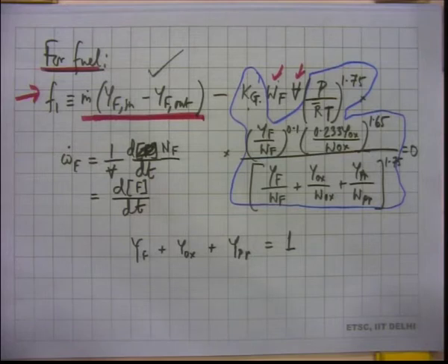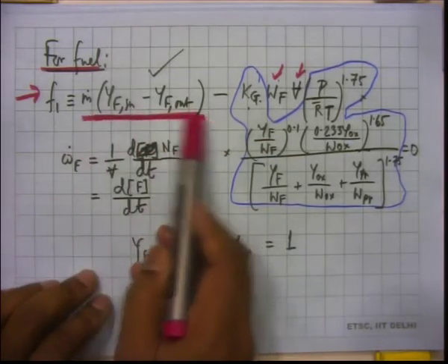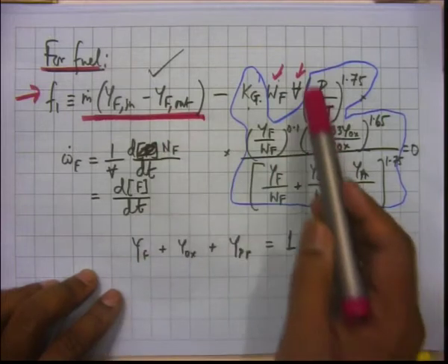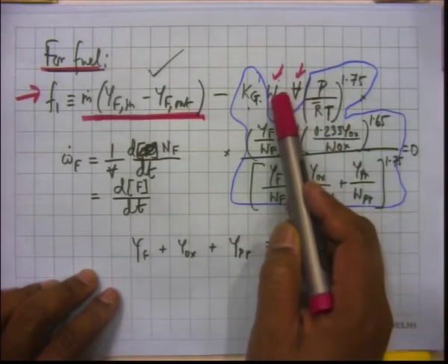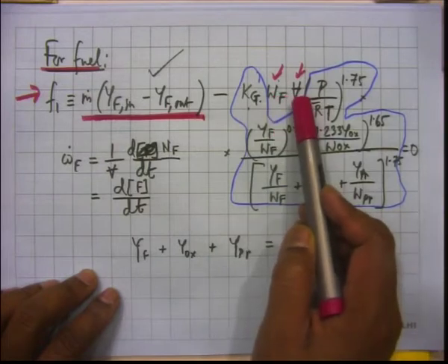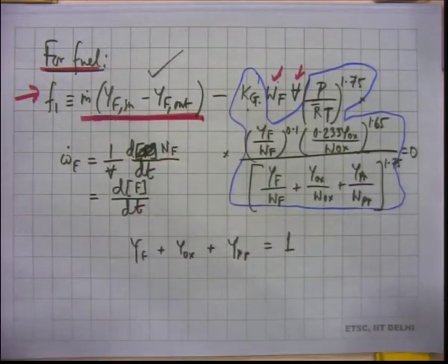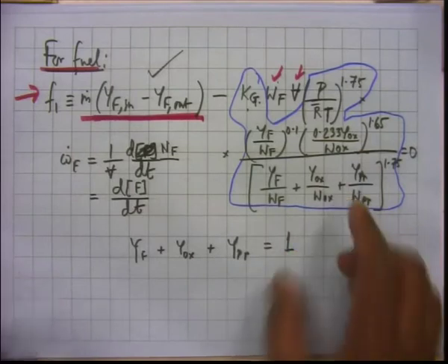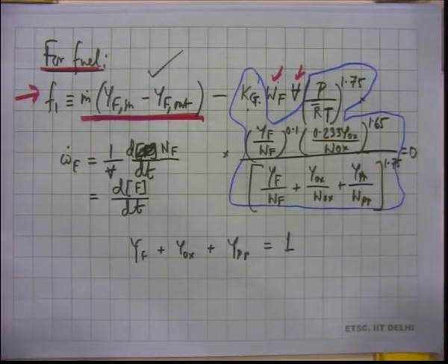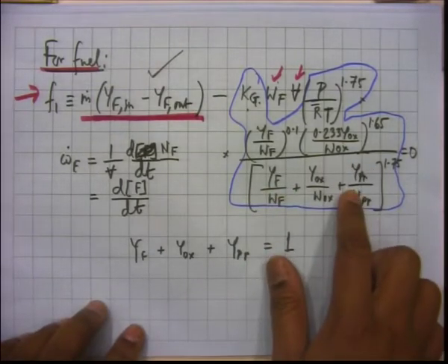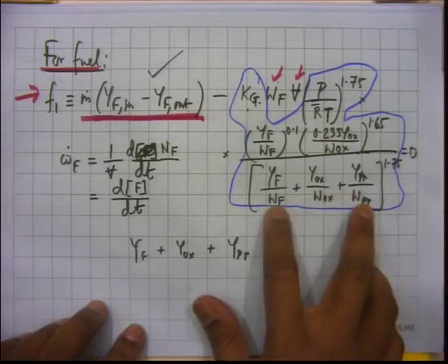Okay. Just to revise, we understand that this should be there in the fuel species equation, no problem with this, correct. And there is also no problem with this molecular weight of the fuel and the volume of the chamber. We understand that there has to be a kg also. So, all this that you see here is primarily because you are converting concentrations to mass fractions. In the process, you got a mixture molecular weight and you wanted to replace that also. So, the sum of these is actually the mixture molecular weight, that has come into the picture.